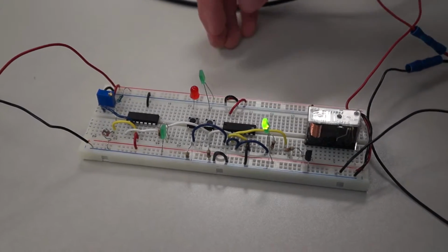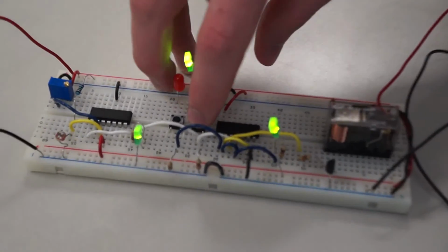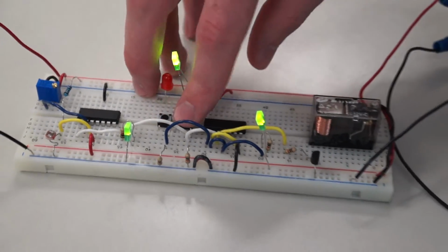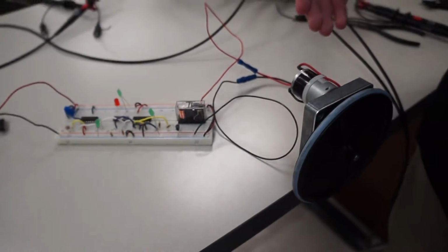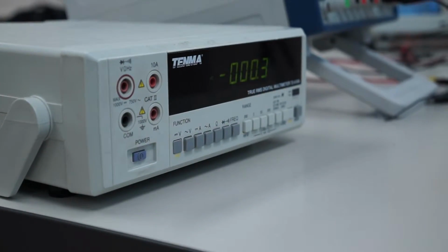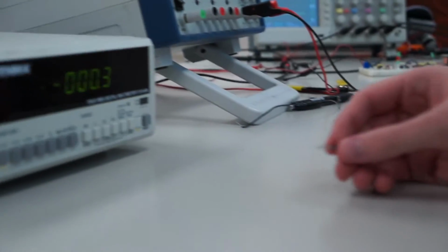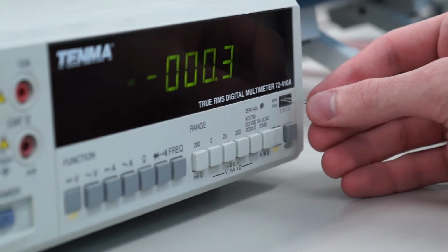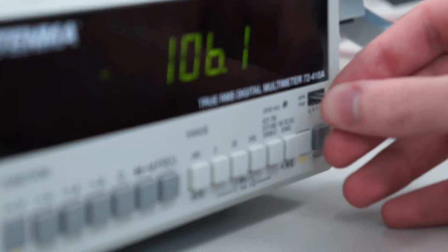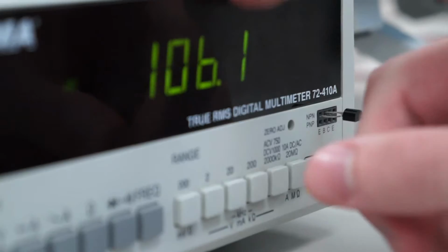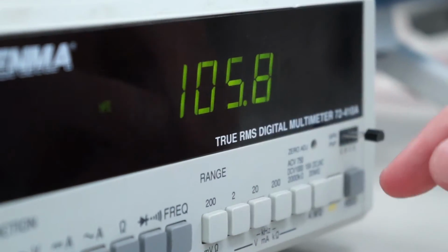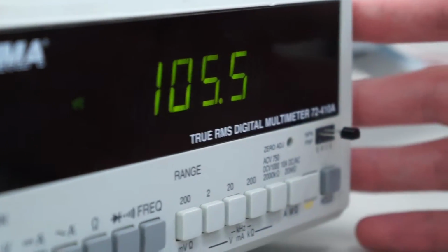Now we see that there's a problem with subsystem 3. So we have to go through, and we notice that it's not latching and the motor's not turning on. Now that we know there's a problem with subsystem 3, there's two different ways to check if the transistor works. The first is to find a multimeter like this and plug in the transistor. And if we get a reading, that means the transistor is working fine. So the problem is not with the transistor.